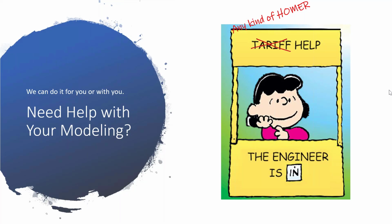So let's say, instead of modeling it out for 20 years, let's model just the first 5 years, and let's design a system that will meet the load, including the load growth, but just for those 5 years. If you're expecting substantial load growth, let's say 10% a year, doesn't sound like a lot, but that means it's doubling every 7 years.